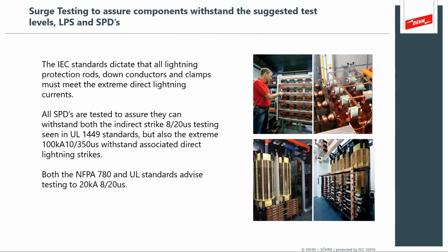And we can see that in IEC methods, these materials all have to be actually tested for the purpose. And this is a real key issue. There are also certain tests relevant for direct strike lightning protection applications that the NFPA and the UL standards don't even recognize. So this is another key aspect.